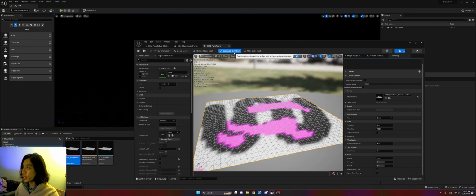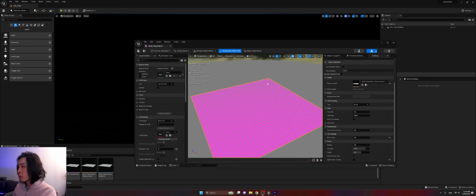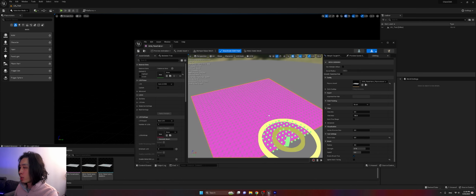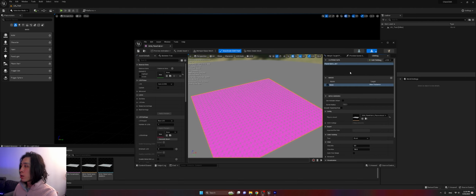So if I deactivate the cloth again, you can see the black part becomes the one that doesn't act like cloth. The pink area represents the default part in a mathematical sense, and in my practice, I don't feel like it has any difference from the 0 black part. As you can see, even right now, the paint value is 0, and I'm trying to paint on it. It doesn't make any difference. If I change it to 100 and then paint it to 0, they become black. So that's the basic logic of clothing data painting.